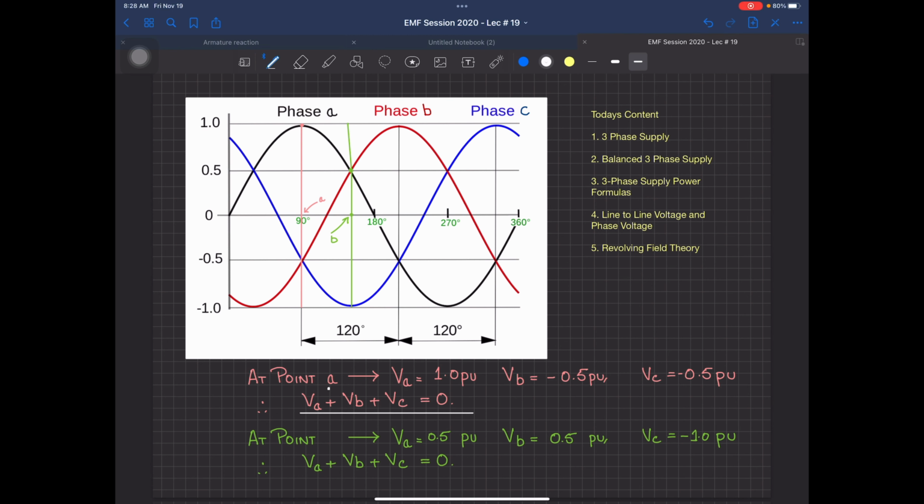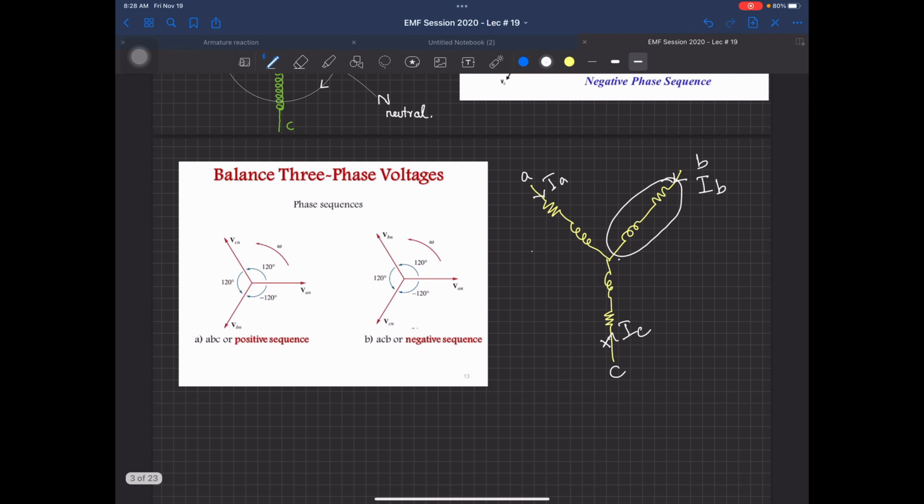But if the resistance or the impedance changes, then certainly you are going to land in some trouble, and the machine is not going to give you a homogeneous torque. What I mean is that the machine is not taking balanced currents. So this is also a check on any machine. If your machine is not taking IA, IB and IC of the same value, there is some problem in your machine.